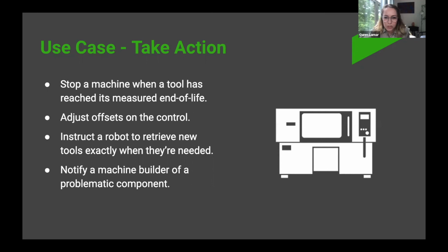If machines are old and don't have standard communication protocols, how can I get my machine to the cloud? Absolutely, yeah. So that's where sensors come in. Sensors are a really simple way. If we have the schematic of the machine, which is a good place to start, there's probably a lot of relays that are available that actually describe what the machine is doing pretty accurately. And then we can use other sensors like current transducers or light pass-through sensors to detect when parts fall out of a part catcher, or that there's power going to the spindle or providing power to some component with the machine. And then we can further describe that as it's translated from the edge into our cloud.